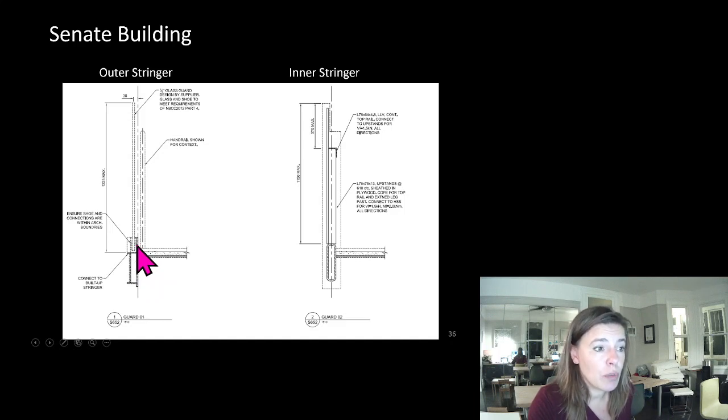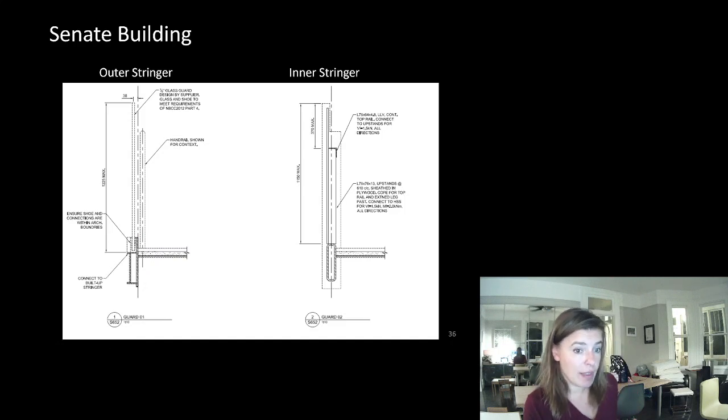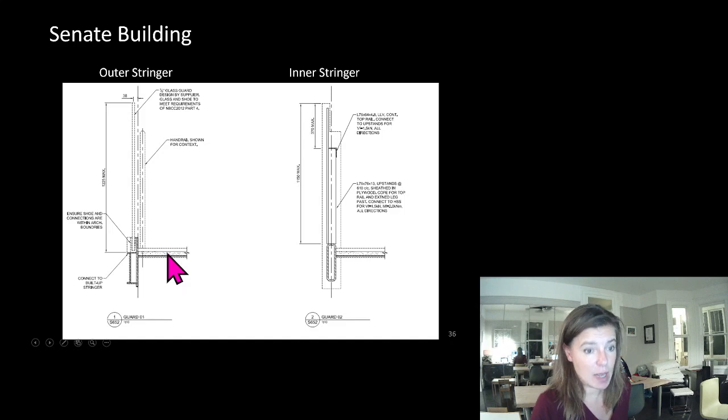During the construction process, the shop drawings I got were an HSS without this plate. And I was like, nope, that doesn't meet it. A, because you haven't met the strength capacity of what I've drawn here. You haven't met the stiffness capacity of what I've drawn here. And you haven't met the architectural requirements that I've drawn here.